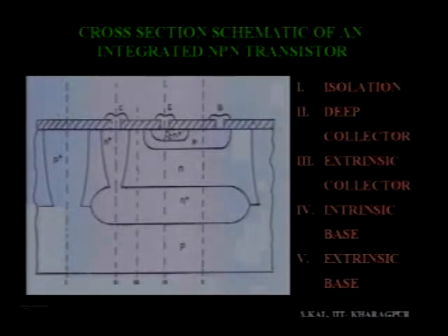From the surface to this region, it will be the N plus dopant, here phosphorus. From this region to this region, the intrinsic base region, it will be the base of our transistor, and from here is the base collector junction. From this point to this point is epitaxy, again N type dopants, and the buried layer is also N type, a highly doped region. The purpose of the highly doped buried layer along with the highly doped deep collector was also explained earlier. So, now let us look into how the doping profile looks.